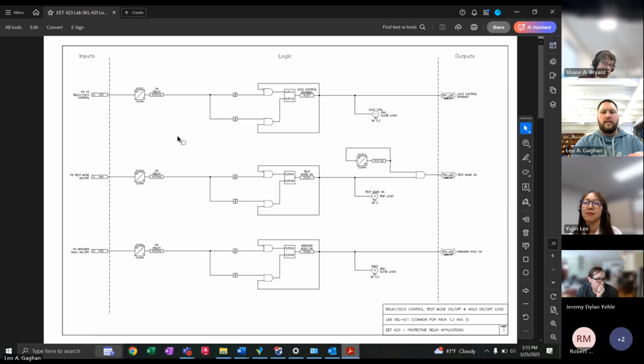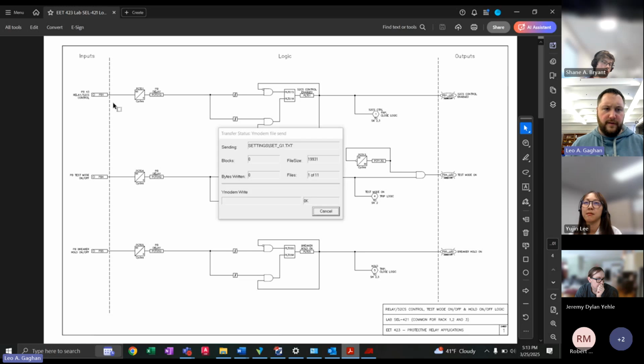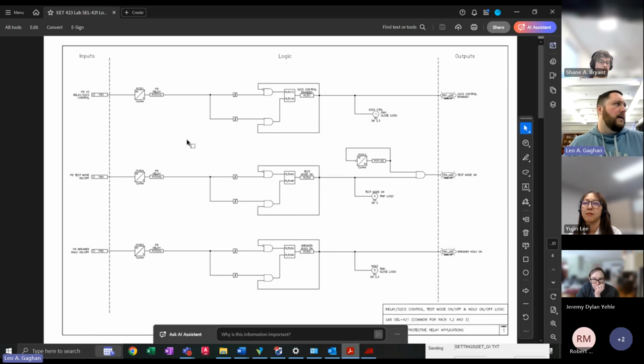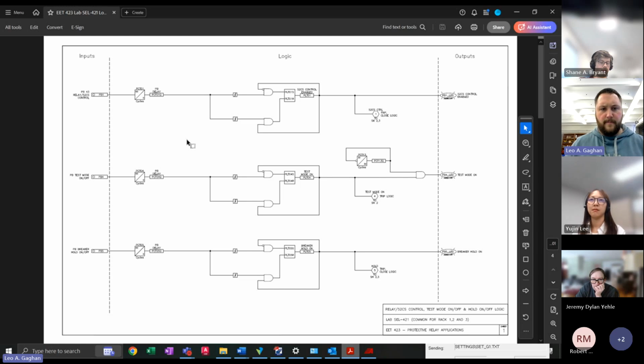So this is a pretty typical logic diagram that you would work with in a relay settings job. On the left side here, you've got the relay inputs. Those could be hardwired inputs, the push buttons on the front of the device, SCADA points, any information coming into the relay. I think in that first lecture, I may have had a table of some typical ones.